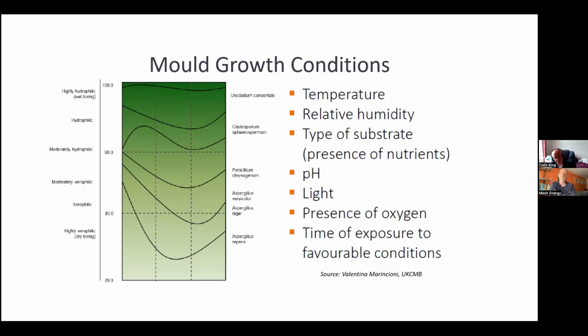You don't get condensation and mold at the thermal bridge because that accelerated heat loss reduces the risk of condensation and mold. But on the adjacent structures, there's a higher risk, which is why you have to reach this fRsi of 0.75, which is a thermal bridging value. It shows that the temperature difference between two elements is not more than 75% out of sync. So internal wall insulation is really, really challenging. And if you do partial insulation, like leave the kitchens and bathrooms in place, then it's destined to fail.